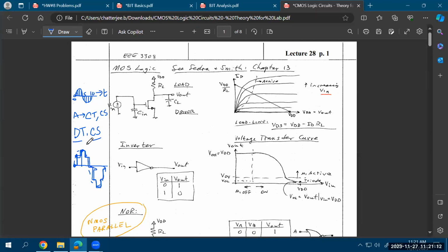So if you discretize both in the time domain as well as in terms of the value of the signal, with certain values, let's say your time is 0 second, 1 second, 2 second, 3 second, like that. And in your signal domain, you have this as 0 volts. This is 1 volt. This is 2 volts. This is again 1 volt, 0 volt. This is minus 1 volt, minus 2 volts, and so on. If both your time and signal values are quantized, then it is called discrete time and discrete signal. And that discrete time, discrete signal logic is called digital logic. That's the difference between analog and digital.